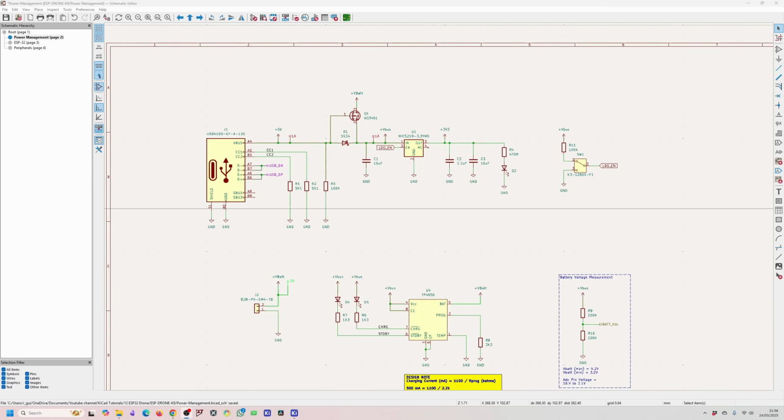This is a battery line on my circuit, so again, a LiPo circuit, and this project is running 4 motors, which obviously can draw a lot of current. So I need to tell the PCB designer, and the people who are looking at the schematic, that this is going to be a high current path and a high current net, basically. So there's a lot of current flowing down this signal over here.